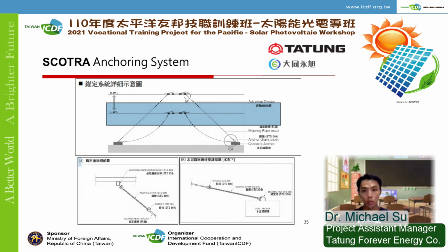Now here is the anchoring method. It is the core technique for sites on the water. This site actually uses concrete blocks under the water to anchor the platform. Below you can see they also use anchors on the bank to help stabilize the platform, and they also have cables underwater. So this is their way for anchoring the platform.